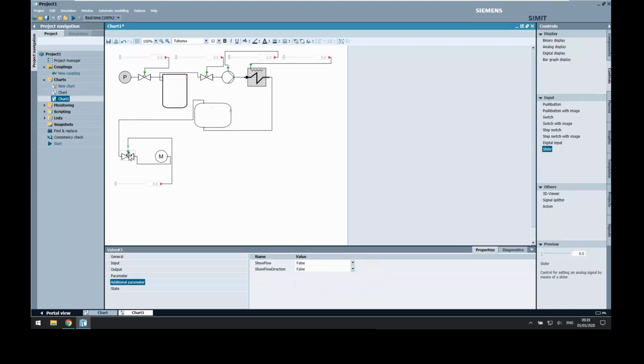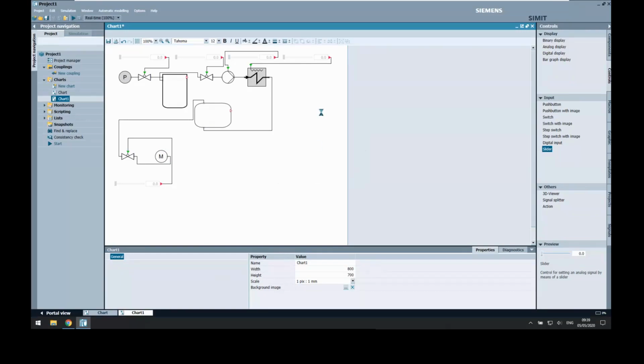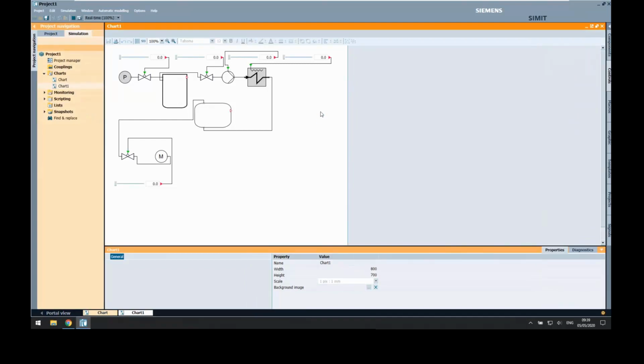Okay, then we have our last valve that regulates the flow to our output. This one is 0 to 100, and the output itself, mass flow of, I have no idea what the consumption of something like this could be. Let's say it will be consuming 2 kilograms per second. So this all should be good now, unless my interconnect is wrong. Let's see what happens. Nice. Okay. So let's fire this up.